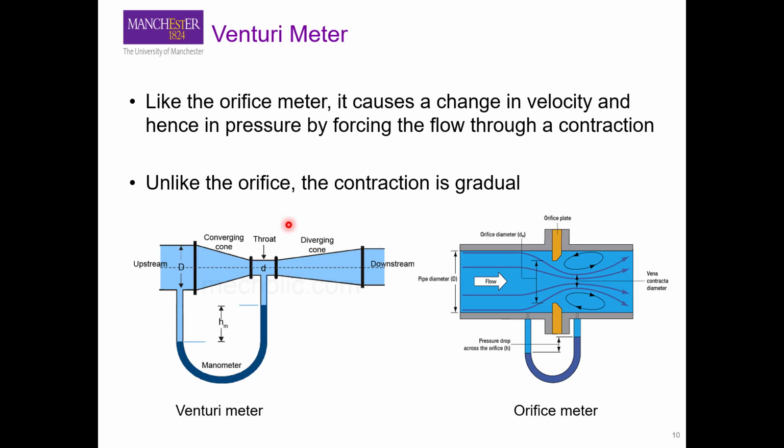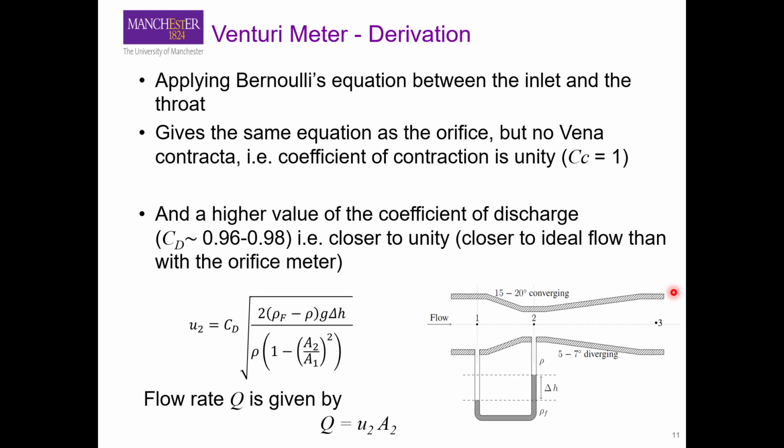Okay, so here, for example, you can see you have a Venturi meter which consists of a converging section, and then you have this short parallel-sided throat, that is this, and then you have again a converging section. Sorry, a diverging section. Okay. And if you apply again the Bernoulli equation, just like we did for the case of the orifice plate, we will get the same velocity equation. If you like, you can try to do it yourself, but it is exactly the same. You consider a point 1 here and point 2 here, and then you do the same analysis.